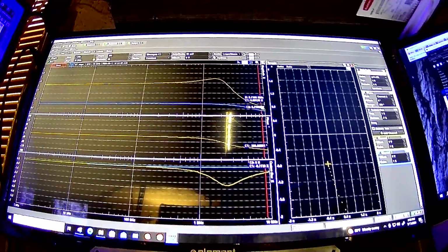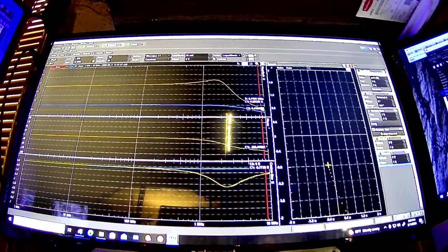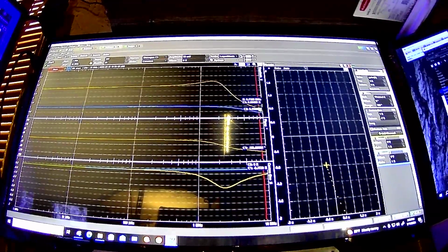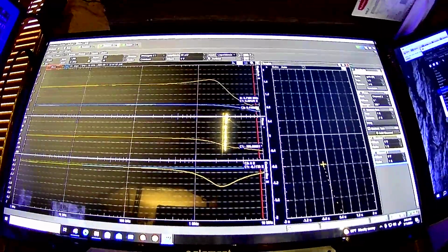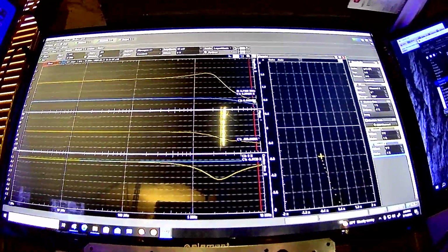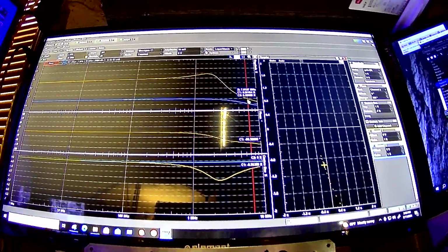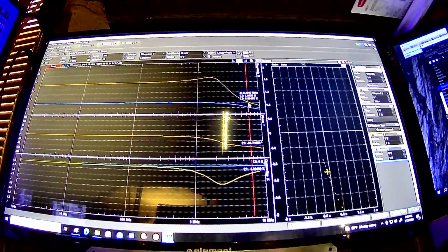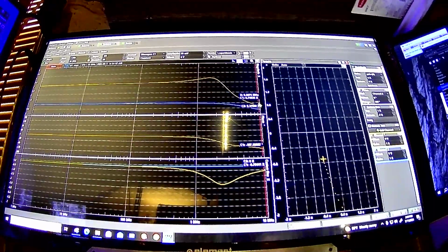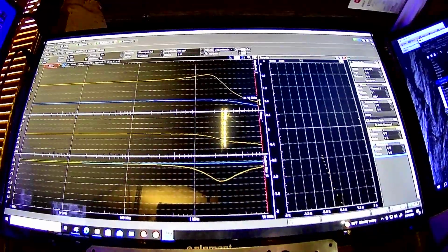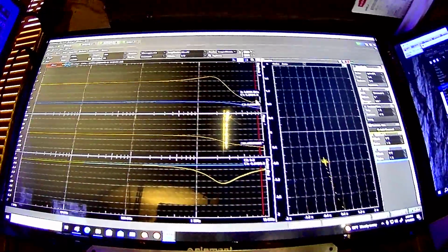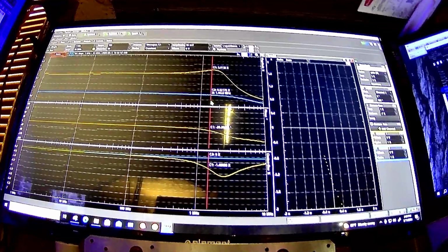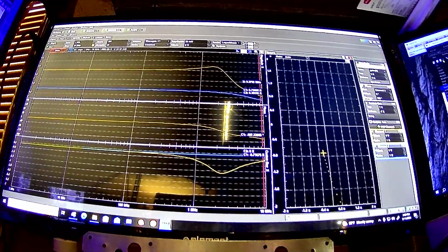That's how it works, but generally you may have trouble doing that with a non-inverting op amp versus an inverting op amp. With an inverting op amp you can get subunity gains, but with a non-inverting one you just generally can't. But at any rate, I wouldn't have been surprised to see the gain trail out here to no less than 1 or so until you get to a high enough frequency, and then it'll all crap out. But since this is rated at 10 megahertz, I don't know. Anyway, I'd have to investigate that. But at any rate, this hump thing, yeah, that's rather annoying.